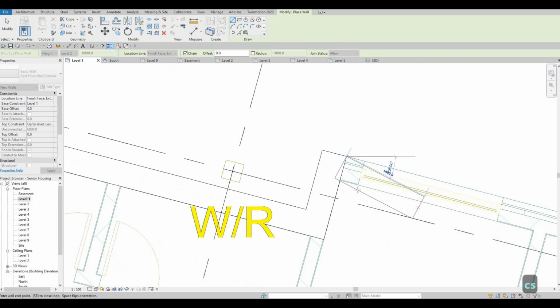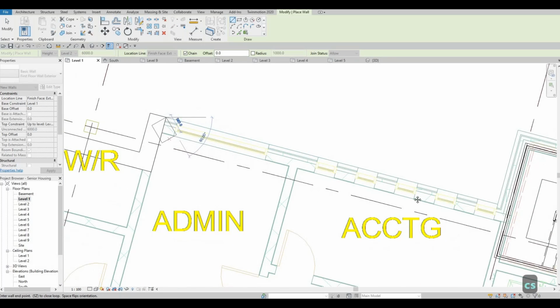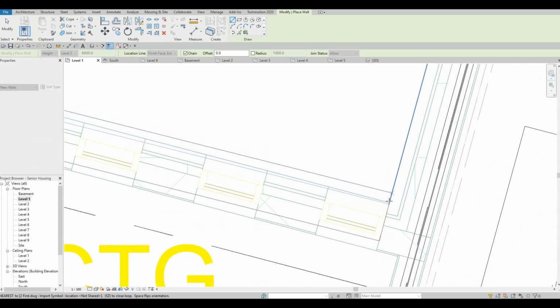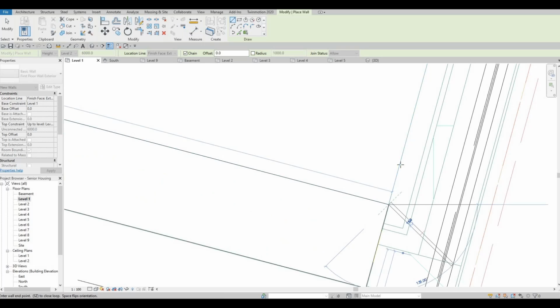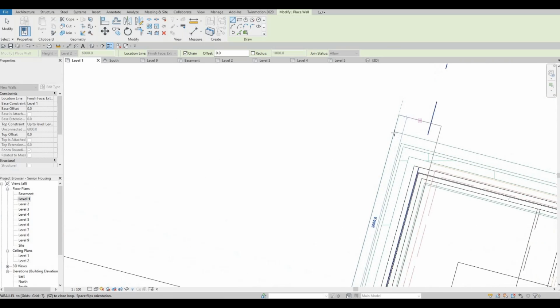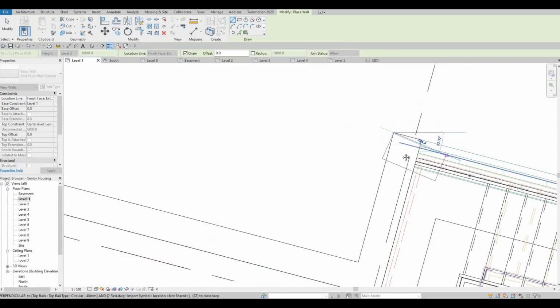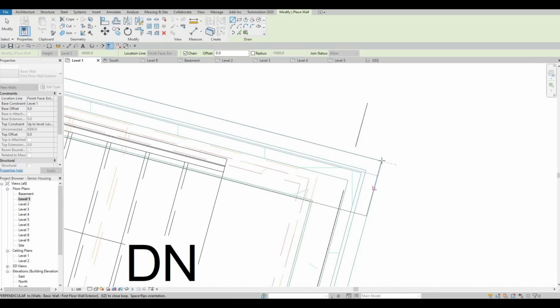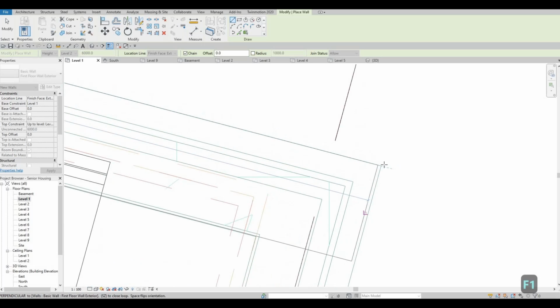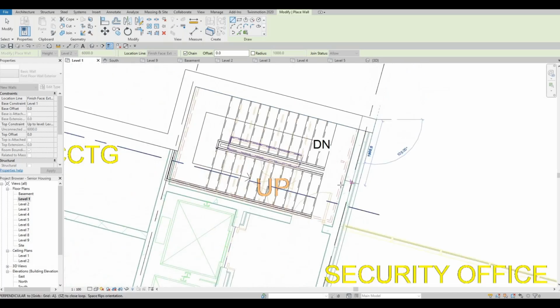That's an easy way of reappearing what you selected. So if you have something like a furniture, you can always press CS after you selected the furniture so that it's easier for you to redo the command. So here I'm just looking for the endpoint,